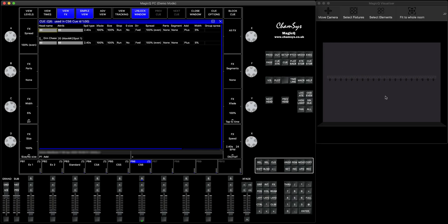So that means the waveform goes approximately like that. So when you run it, because we made the width very narrow, it actually starts from the middle. So how to fix this? For this, if you look in your View Effects window, you have an option here called Initial Offset. So what you need to do is shift that middle point to the left. So that way you will be able to achieve your result.